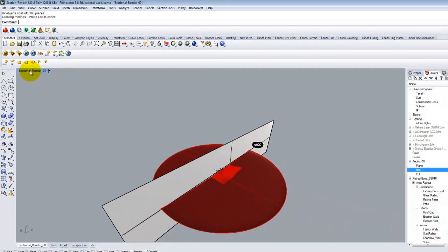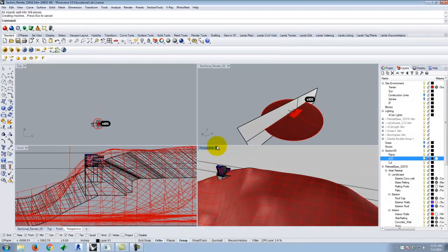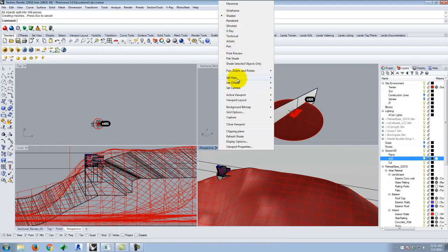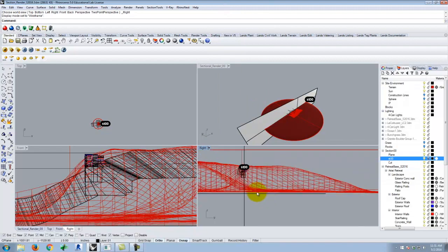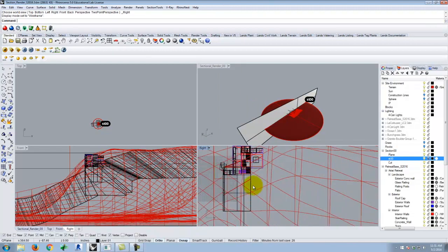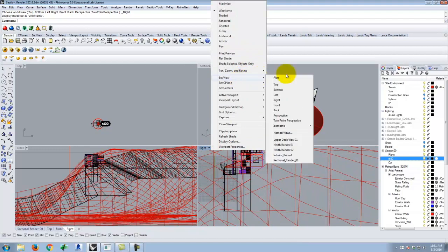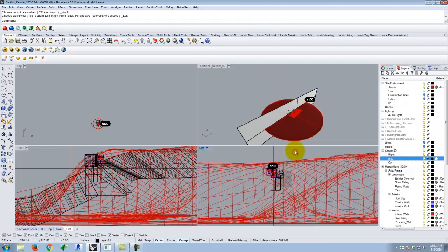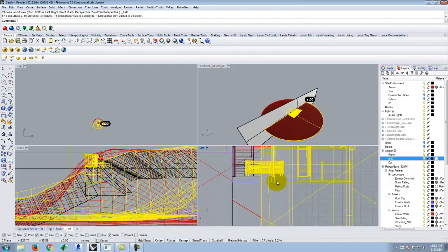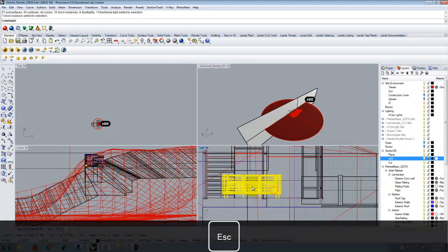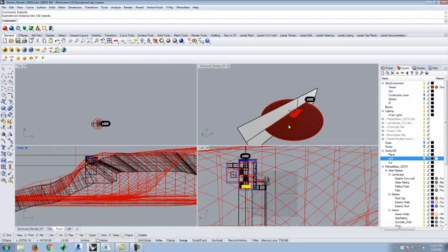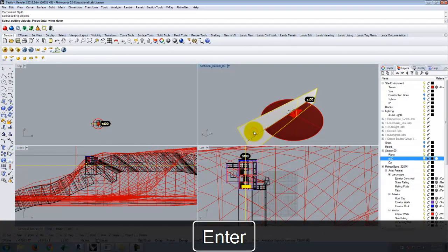And so now if I were to look at this in the side view, let me turn on the right side view. Let's go to Set View Right. And let's go to wireframe here. Okay. When I look at this, let's actually go to Set View Left instead, just so that I have an easier time selecting it. All of these objects, if I did it correctly, should select. Looks like the couch didn't split correctly, so I'll need to take the couch and explode it. And then we need to split the couch with this.